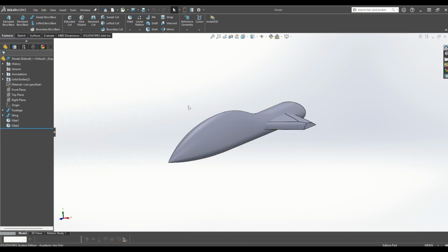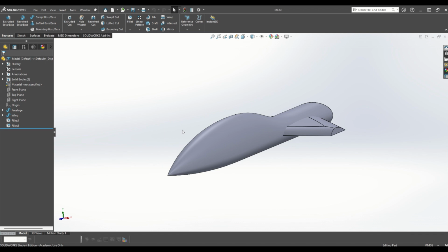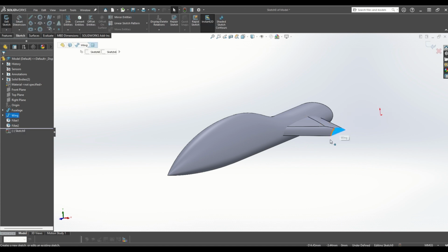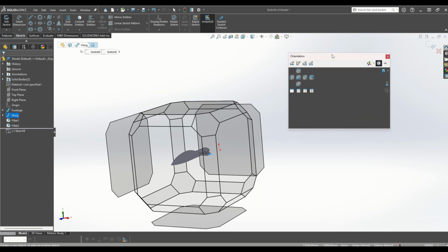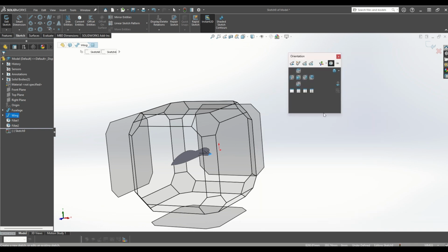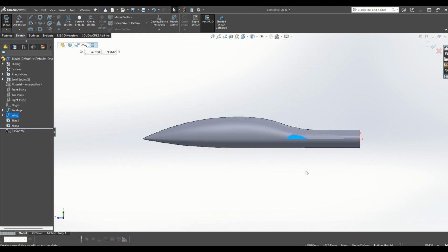Right, so next we want to put in the sketch for the engine of our spaceship. So I want to click on this edge of this face of my wing that I've just created, just the edge that I've created the fillets on here. I'm going to click on this, hit sketch, and then hit my space bar, go normal 2. It's popping up on my other window now because this part of the video is being recorded at a different time to the other part. So yeah, normal 2.